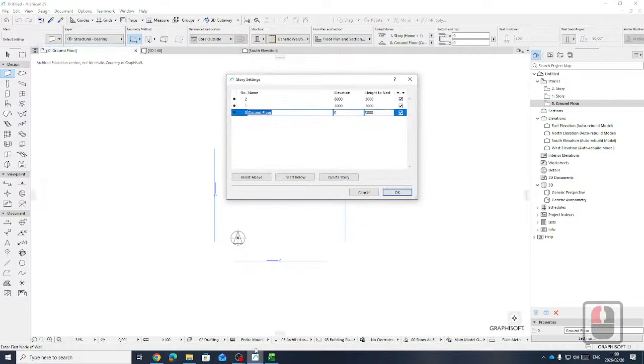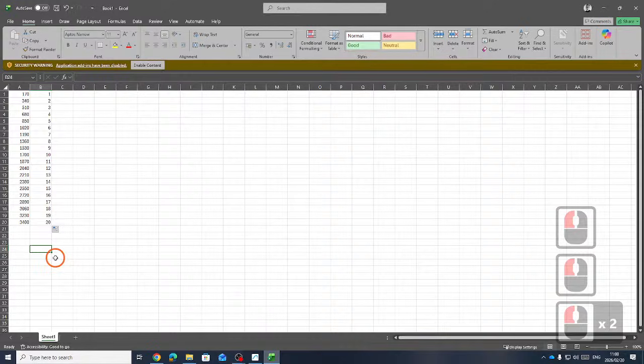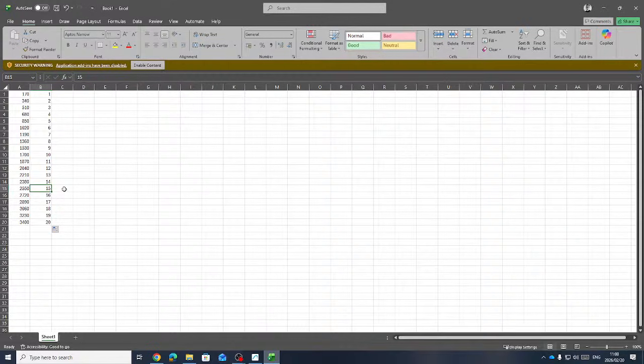Okay, so I'm going to go and look at Excel. So I can keep doing a bit of maths, but in essence, I'm going to use 15 courses from top of finished floor level to underside of ceiling. You can make it 2,380, so maybe 14 courses. Suspended ceiling, that's fine, for an office, for example. Then I need another 510, or maybe 680 for services. It's typically 600 to 500, depending on the, okay. I think Aubrey specified 600 in his lecture for a service zone. Then you need the floor buildup.